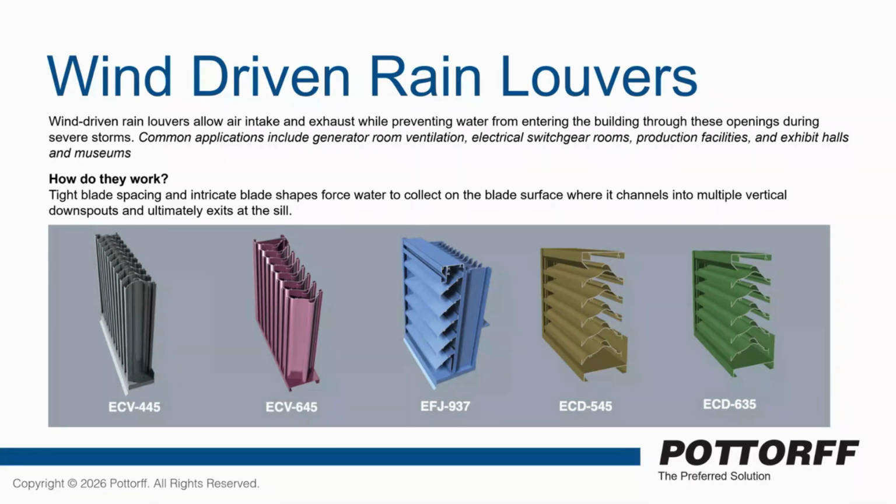The vertical blades on it, I can tell you, vertical blades are going to be the best performing blades that you can buy from a louver at keeping water out of your opening or your ductwork. And that is just because as water gets blown in or sucked in, if it catches any type of channel or blade, it's going to follow that blade all the way. It's going to be directed down to the base of that sill and run out the louver there.